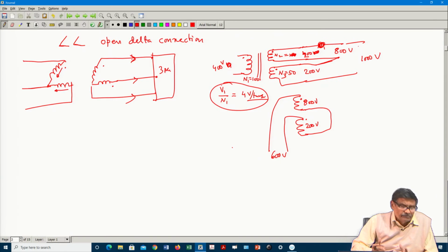So, why is a revolving field not present? It is a very common viva type question people will be asking, but the answer to this question is interesting to explore. A rotating magnetic field is produced by a balanced 3 phase distributed winding over the periphery of a cylindrical structure. You have a balanced 3 phase distributed winding, which we have discussed at length, and it is because of that the rotating field is produced.